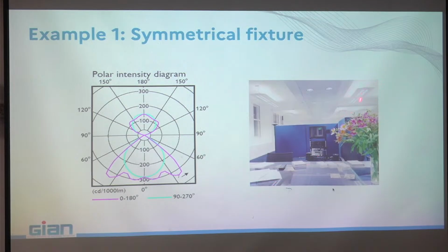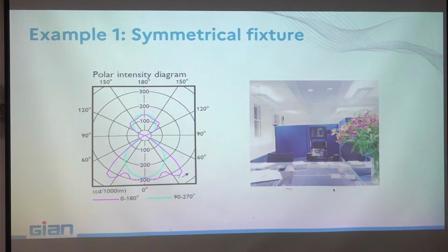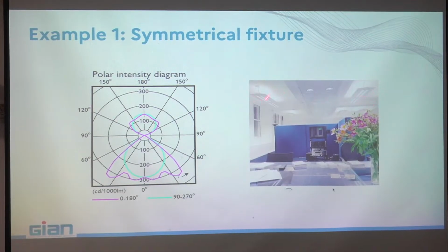That means, as the distribution is very constant, you can illuminate very effectively and with good uniformity just under the luminaires. Here you have one here, one there. That means by using that luminaire you can have a good spatial uniformity that is requested by the standard in order to have the best visual performance.